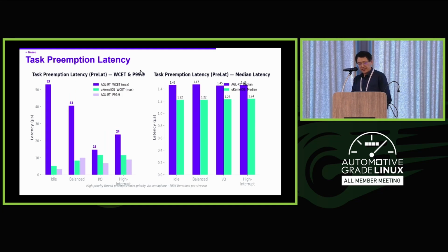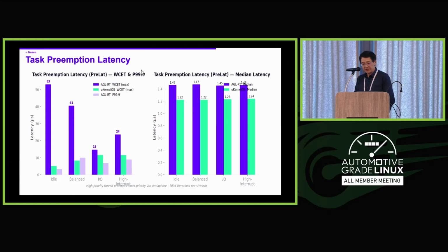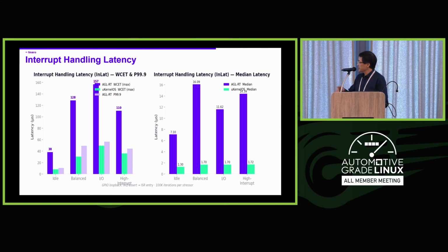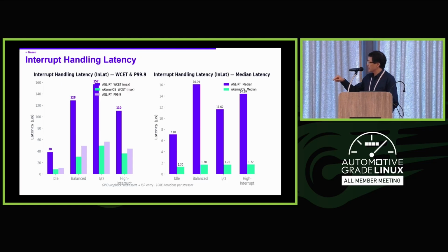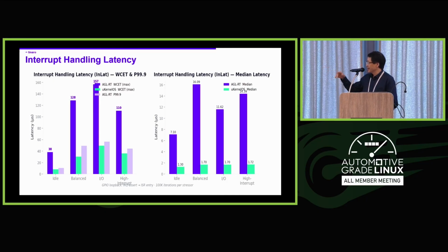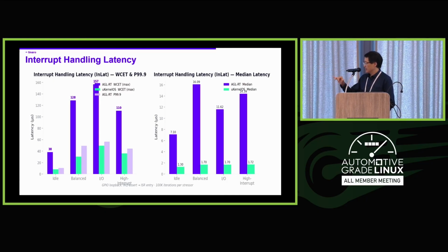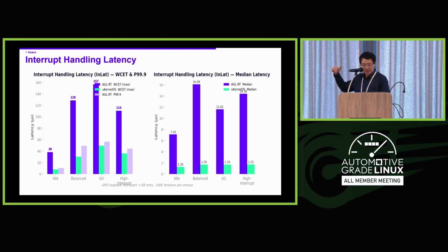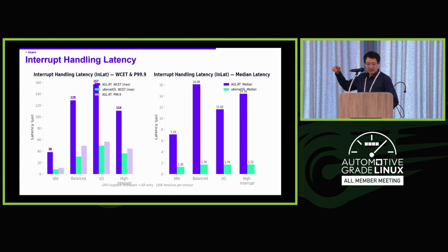And this is for another OS primitive, the task preemption latency. And this is interrupt handling latency, whenever we're using GPIO loopback, whenever GPIO asserts and the bottom half kicks in, processing that event, right? So we capture the delta between these two events. And you can see the worst case execution time is in the IO storming case, the interrupt storming stressor case, goes to 157 microseconds.